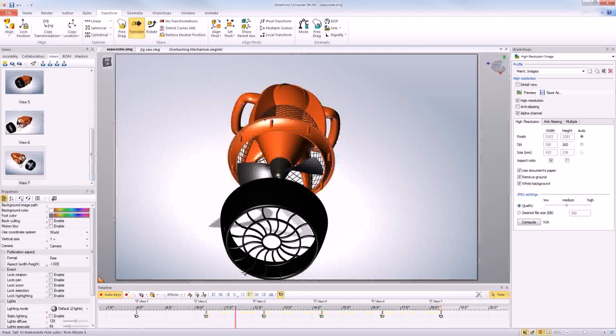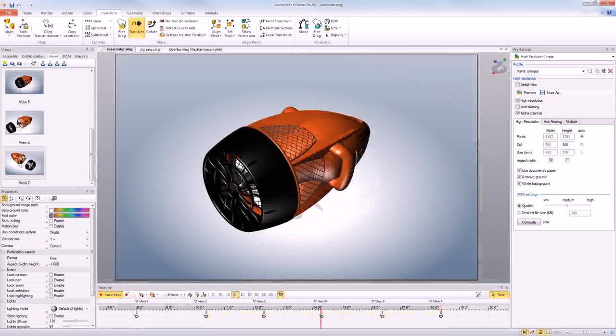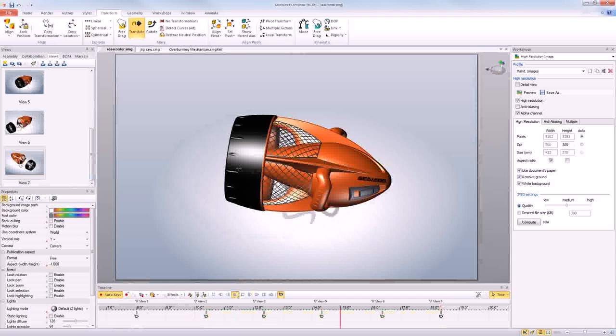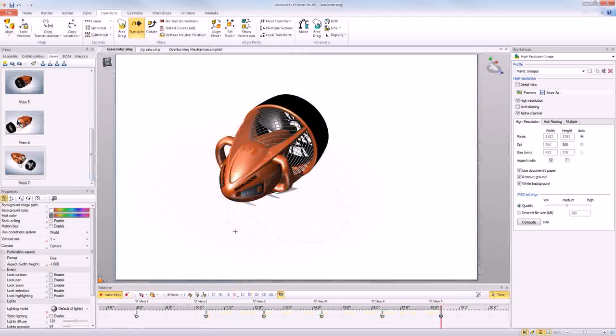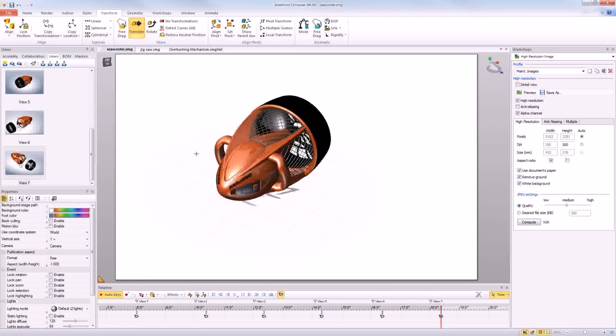And actually, even with this simple assembly over here, when I hit play, even though only this black item is moving, this black cover plate, it's a little stuttery as it goes through to create the animation. That's because it's capturing movement for all the components, not just for the black item that's moving. So something I really like to do is to clean up the animations after I use my view tools here by getting rid of any redundant keys.